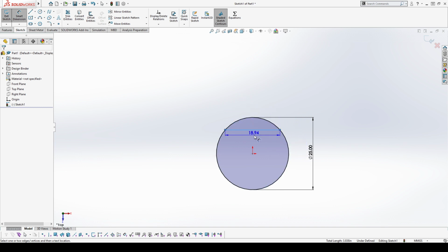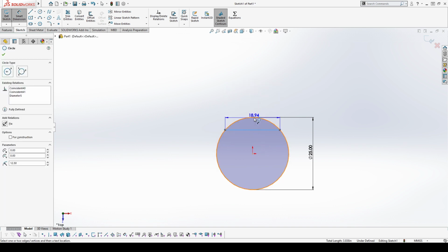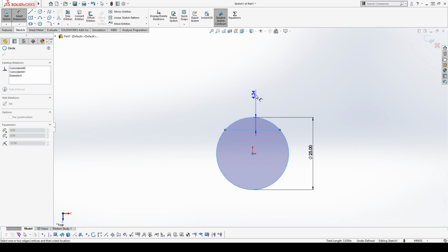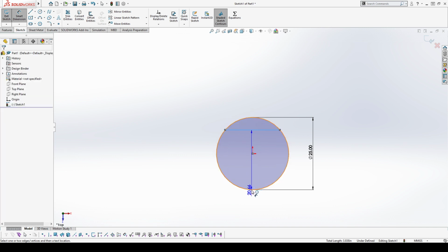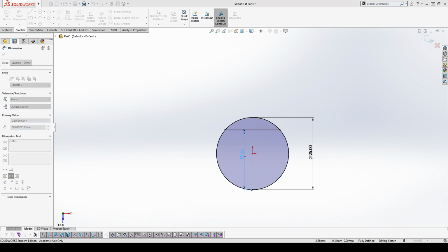The way that I'm getting to that is by holding down the shift key. So remember, if I were to just click on that, it goes to the radius. If I were to click on that while holding the shift key, it gives me the dimension closest to that side of the circle. If I were to hold the shift key and go out here, it's going to give me the opposite. So it all depends how you want to communicate the same information. Either I'm cutting away, as we were doing before, 3 millimeters, or I took this shaft and measured from modeling a part that's already being manufactured by somebody else. Purchased a motor off the shelf and it has a keyed shaft, and I measured from the flat down to the other side of the shaft, and it's 22 millimeters.